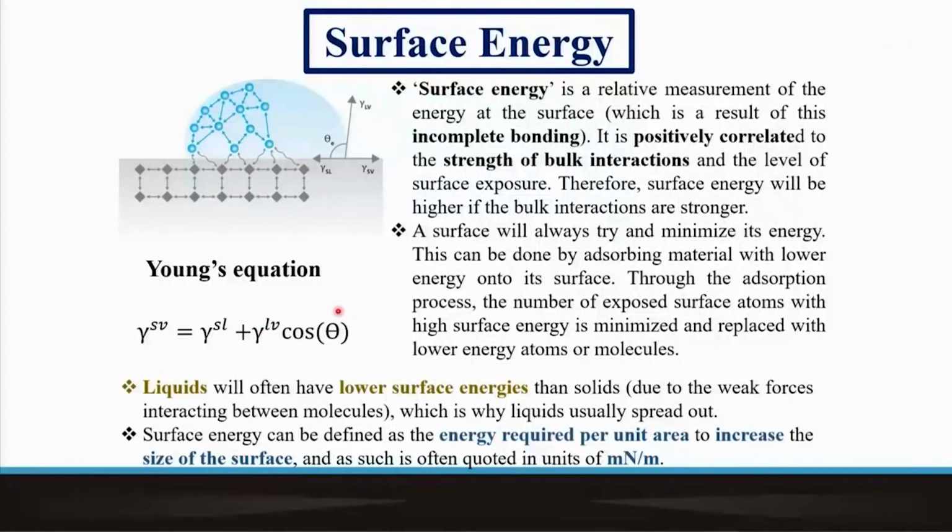So that allows us to essentially determine the geometrical factor theta, which is the angle subtended between the forces, as can be seen here. And we can easily make out that depending on the chemical nature of the droplet and the solid and their interaction at the interface, the angle that is subtended varies. And hence this angle, the so-called wetting angle, is a very important and convenient parameter to describe the level and the kind of interaction between the particular solid and liquid under discussion now.